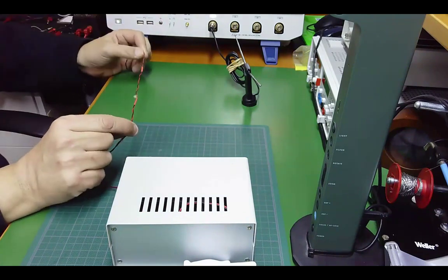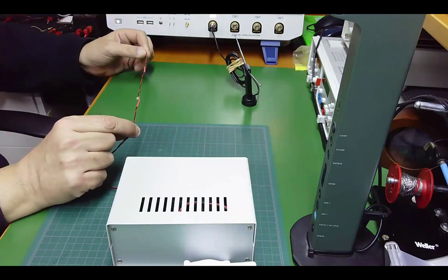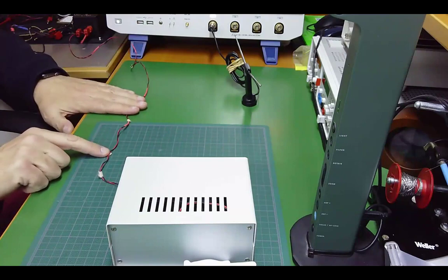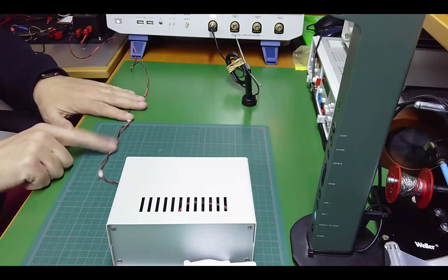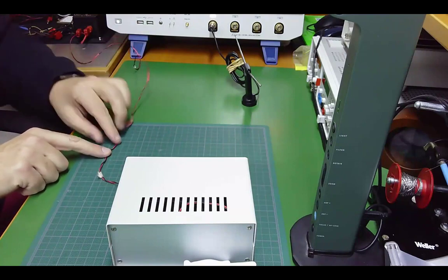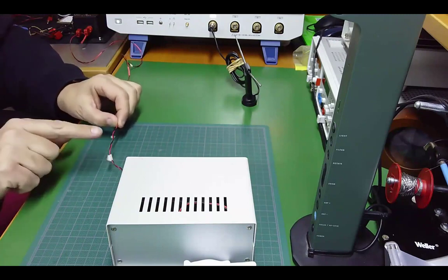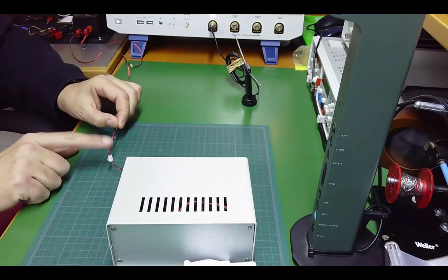If the cable is horizontal, we'll be radiating horizontal electric fields. So now that I consider that the noise is being radiated by the cable, I have two possibilities: is it differential mode or common mode current? Usually in cables, the origin is common mode.